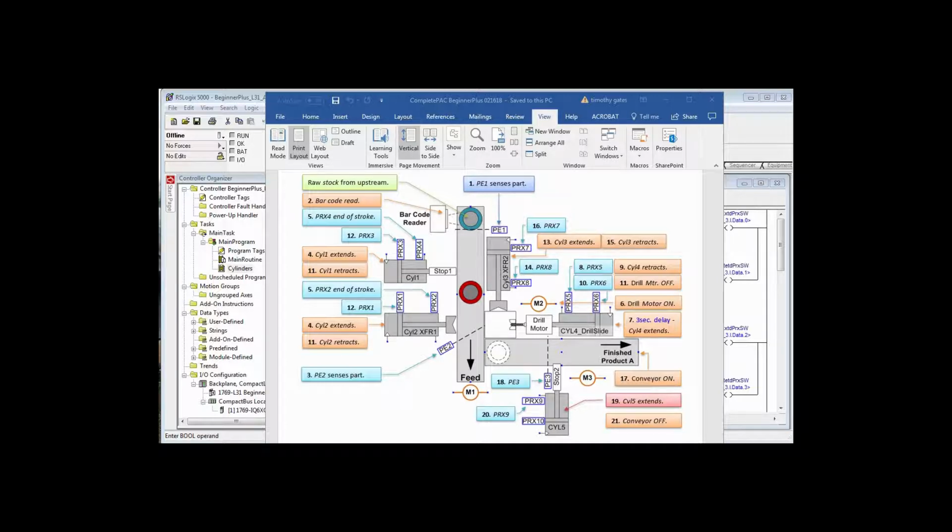Now we may want to put a delay in between 8 and 9, meaning, remember that these proximity switches, Hall effect sensors, whatever they are, are adjustable, meaning that you can adjust them at the ends of stroke, retract and extend. They just go on when it's fully extended and fully retracted, or maybe it goes on before it's fully extended and retracted, and there's a little bit more motion there. In most cases, you want to add a little delay before you say it's actually extended or retracted, just to make sure it is.